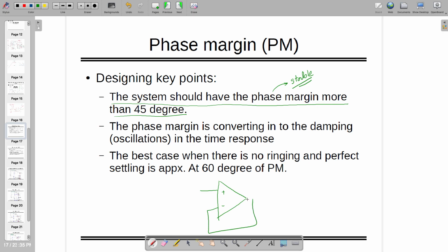So, you must have seen this kind of circuit. Have you seen it? Yes. If I am applying a square wave here, what will be the output? If you are solving any operational amplifier, you are going to follow two rules. One rule says, what is that rule? V plus equal to V minus, and no current flows inside, right? These are the two things you need to remember.